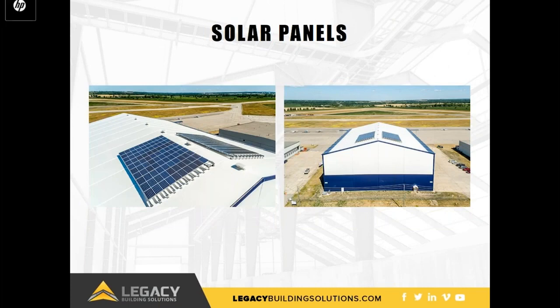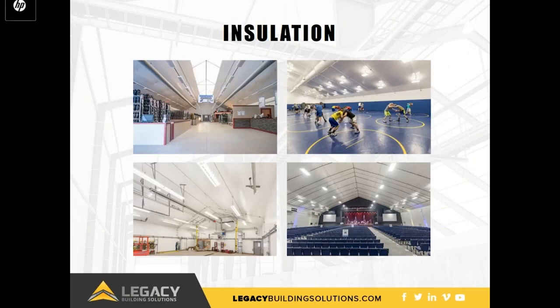Roof-mounted solar panels are installed parallel to the roof beams for maximum sun exposure. The extra load of the panels and racking will be accounted for in the building design. Occupied buildings will require insulation for year-round use. Batten insulation up to R30 is available in the walls and roof of the structure. In insulated buildings, an interior liner will protect the insulation and provide a smooth, bright finish to the building's interior.